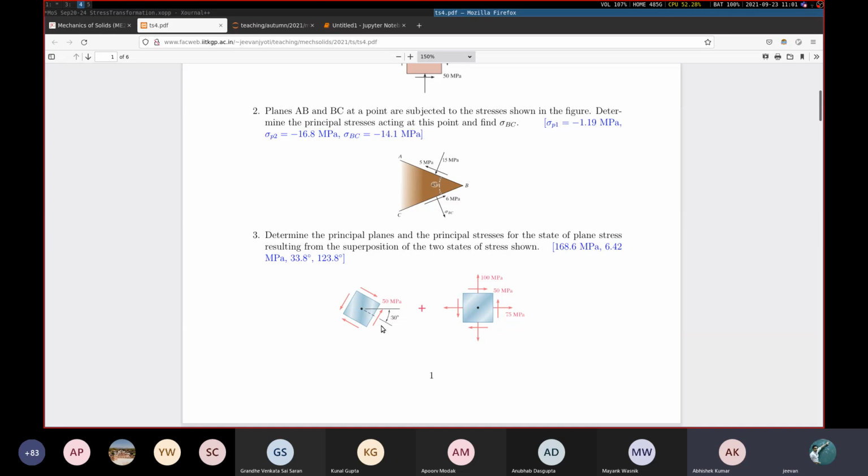Okay. All right. So you were saying this 50 megapascal that has to be transformed. Yes, sir. So you said we need to rotate it. So we need to geometrically just rotate it, or we need to transform the stresses also. Transform. Geometrically only rotate and then you don't transform. What kind of business is that? When you rotate it, you have to transform everything properly. Otherwise, I mean, you're just tilting the computer. That is equivalent to that.